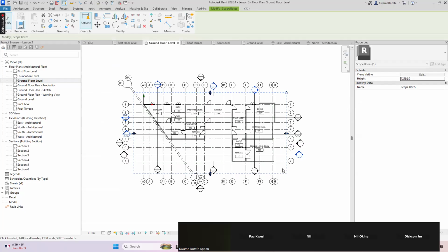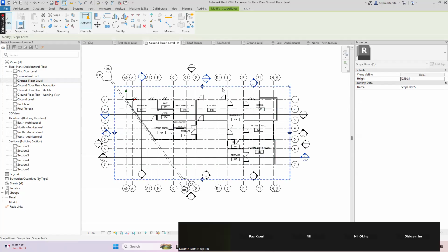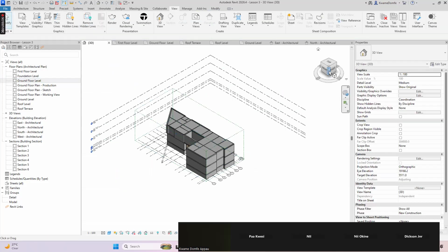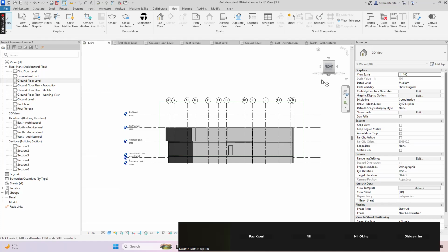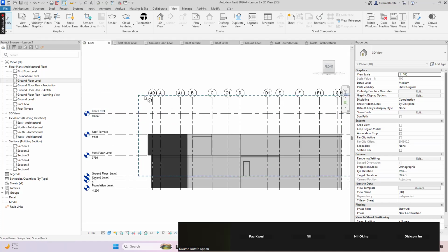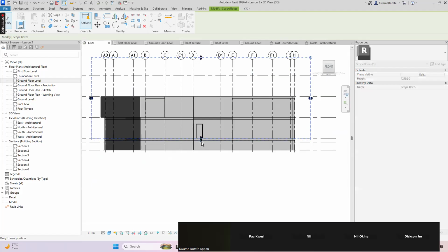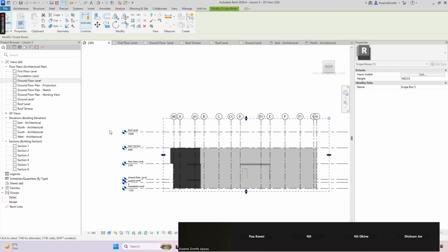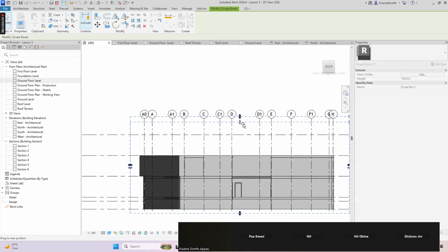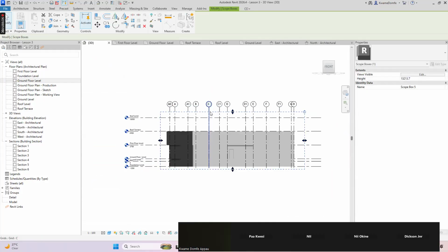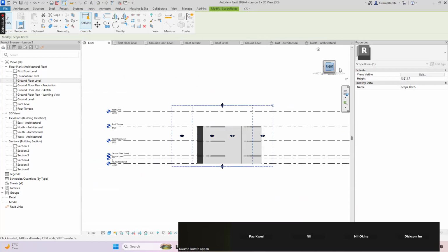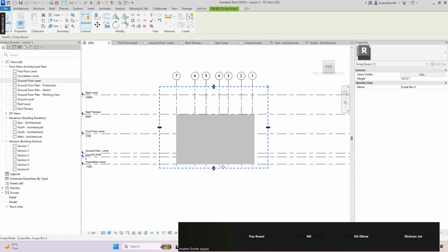That's what I've done here. So if you look at the box that I've drawn, it puts the building in a nice box. You understand? Yes, sir. Then I'll go to 3D view. When I go to 3D view, I'll see that box encasing the building. So I must adjust the box so that it comes below the foundation and just above the roof level. So that the building will completely be enclosed within that box from the foundation to the roof level. Any question?